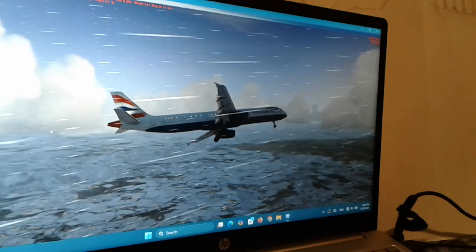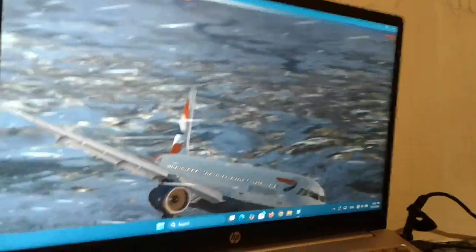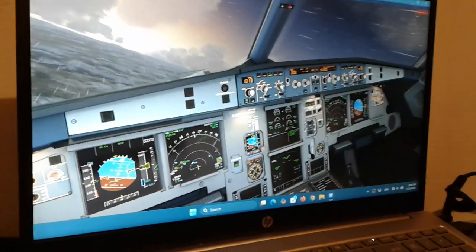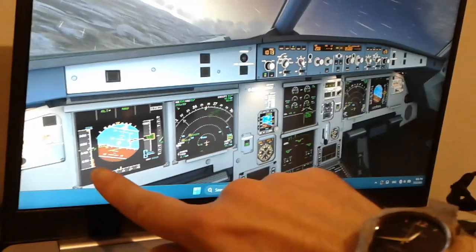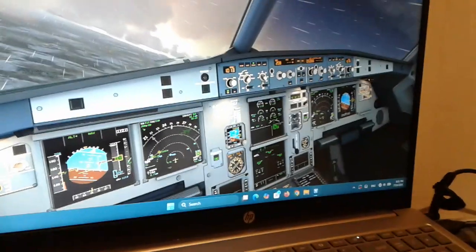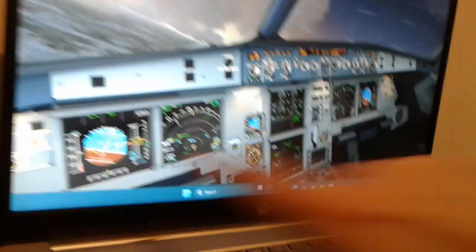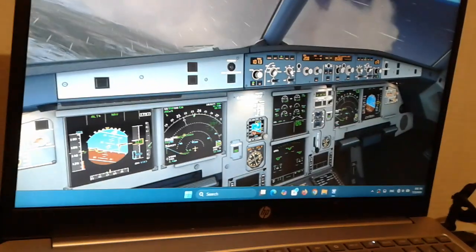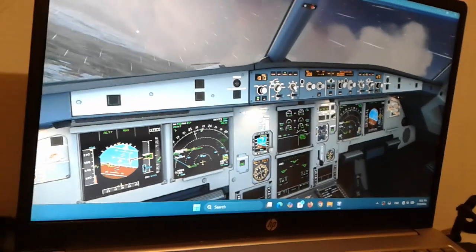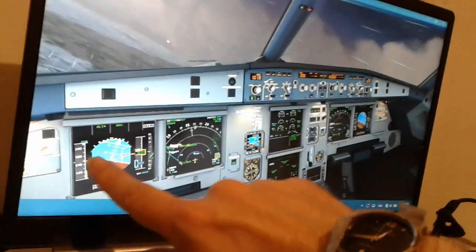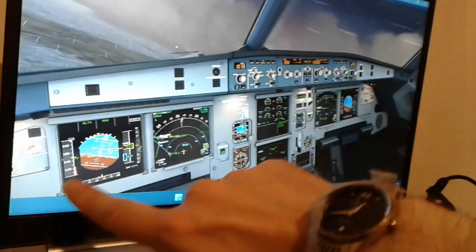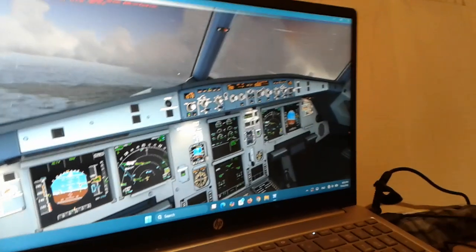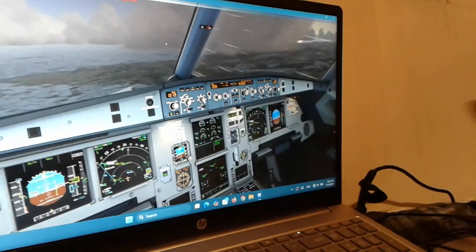Here we are for approach and landing to the airport. You can see the wing. You can see the stall speed here we need to avoid. So we're gonna keep some airspeed above the stall speed, because otherwise the aircraft will lose its lift from the wings and crash. So we need the airspeed always above the stall speed. You can see the red over here, in the red airspeed is not good. Red and yellow and some black.